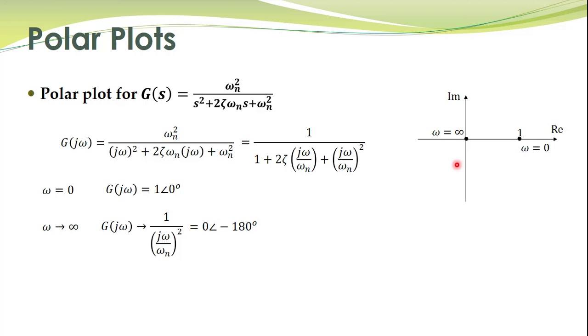Right. So it will cross the imaginary axis. The angle will become more and more negative. It will become more negative than minus 90 degrees, and the graph will be somewhat like this one, starting from here, moving this way, and finally converging to this point. So do you think that it will cross the real axis on this side? Is it possible for the graph to start from here, move like this, and then reach over here? No, because the angle is not becoming more negative than minus 180 degrees. So the maximum angle that is possible is minus 180 degrees.